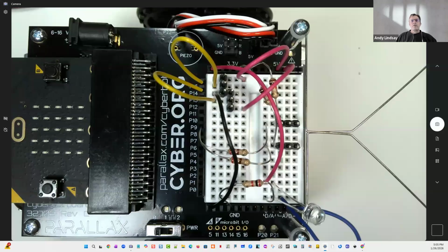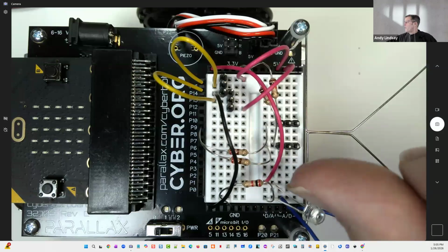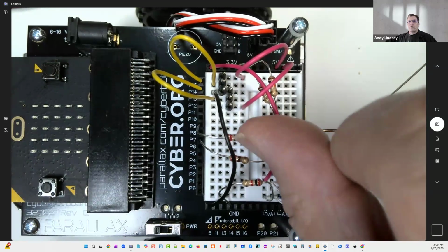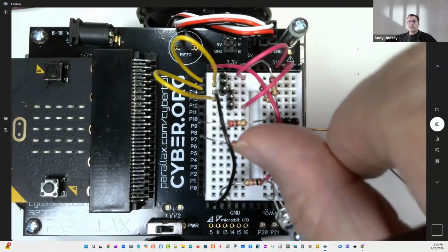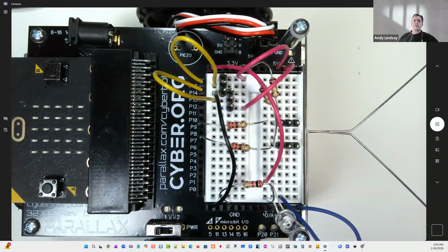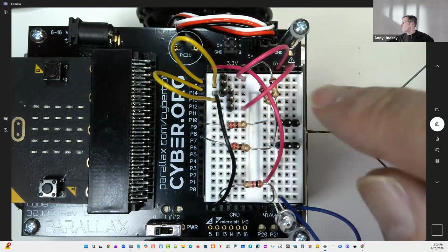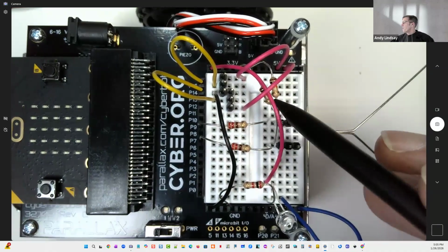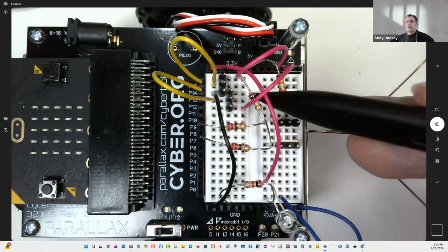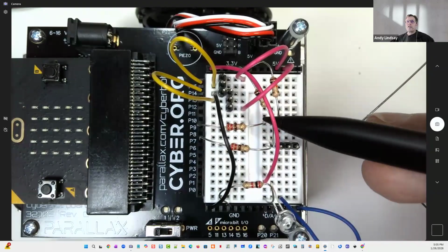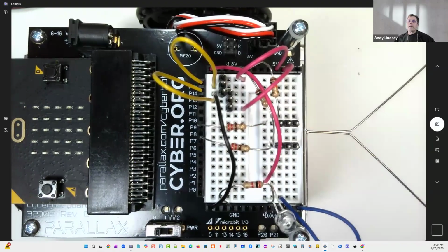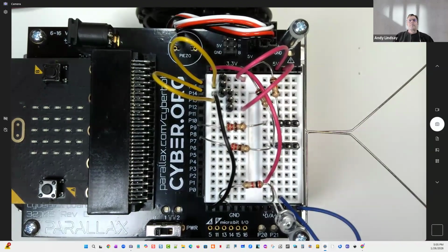Okay, so go ahead and double check your wiring. Also, I noticed that I squished some whisker wires together. That's not necessarily going to be a concern today, but it's best if you keep your whisker component leads from touching each other.